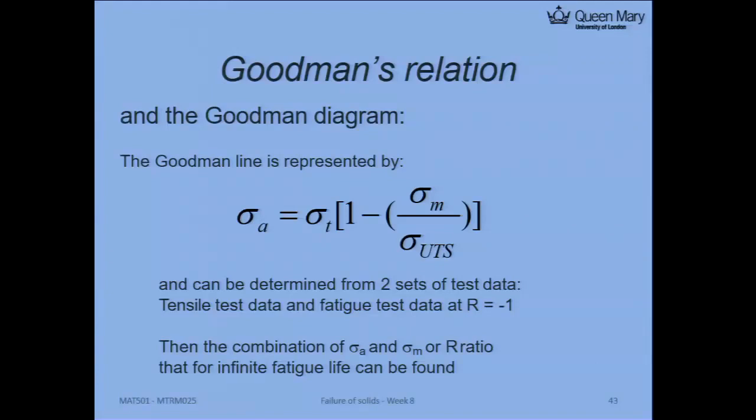Okay, so the aim is to find the infinite fatigue life. Basically, it is this fatigue limit part, and just to reduce your stress amplitude. So suppose you design a bridge, and that bridge can tolerate some maximum load. That maximum load will eventually be relevant to your stress amplitude, right? To have like 20 years of fatigue life. So eventually you will be telling the engineer how to design such that you have an infinite fatigue life.